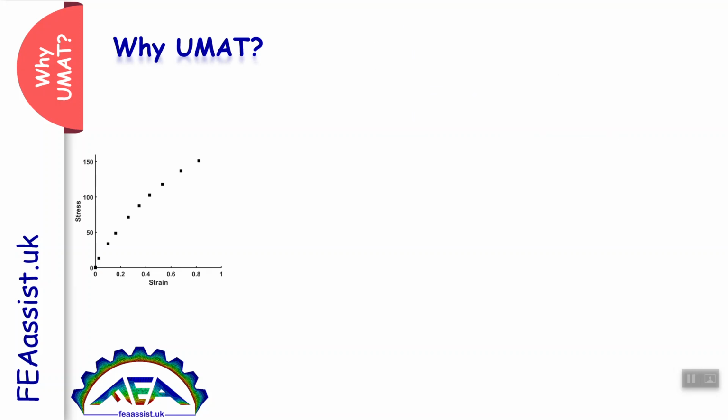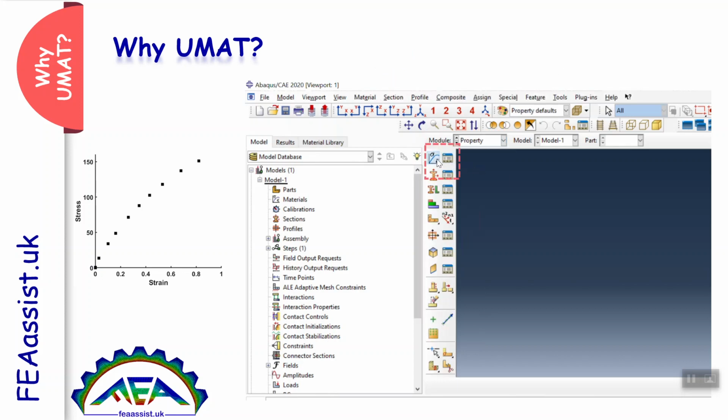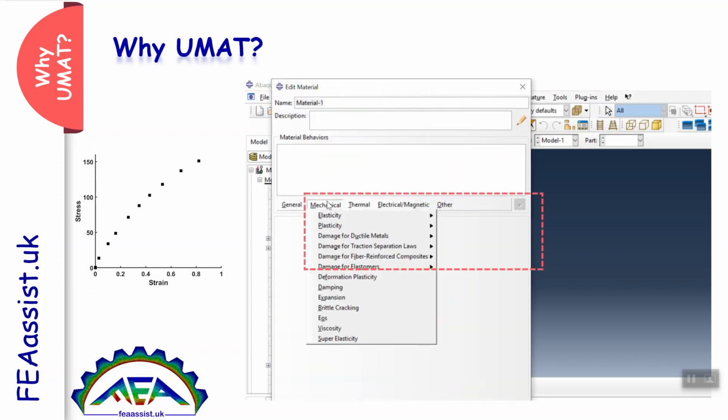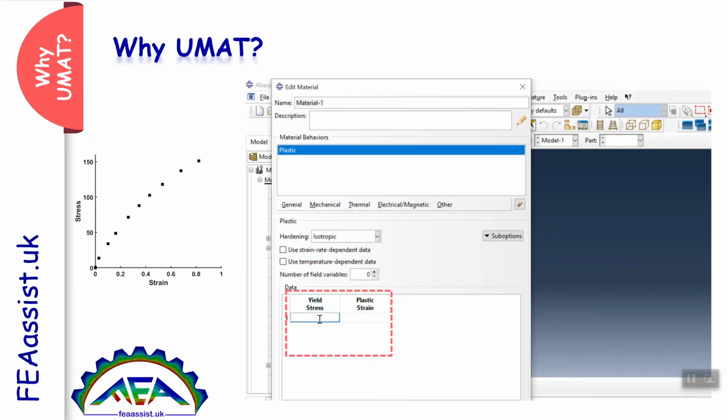The first strategy is that you have some points of your stress strain behavior from lab or from published experiments. You can easily go to Abaqus, to the property, define a new mechanical behavior, plastic behavior, and enter those points like this.